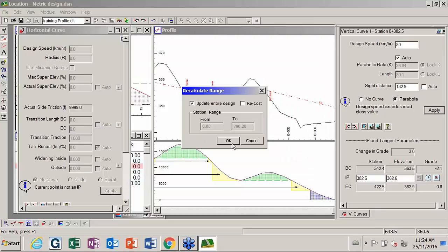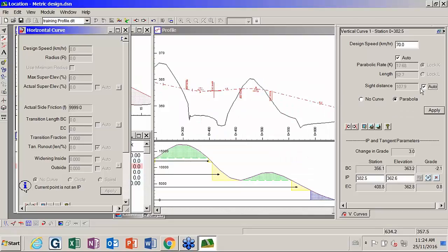If you want to have a little bit increased safety on that sight stopping distance, let me just change this to 80 and apply, and then that's the minimum sight stopping distance. So let's say we up that to 135. That will give me a little factor of safety. Set that as my default curve, jump forward, get my default curve, apply.